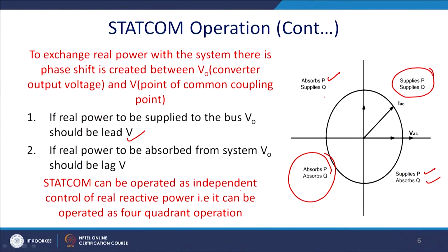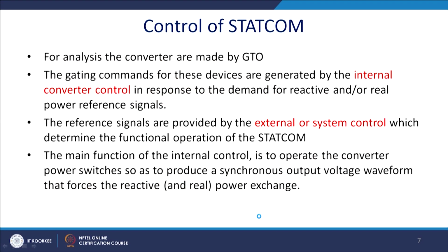Thus, Statcom can be operated as an independent control of the reactive power. That means it can be operated in fourth quadrant operation. This is the flexibility: when you put it with a storage element, its capability enhances. So, let us see how Statcom can be controlled.